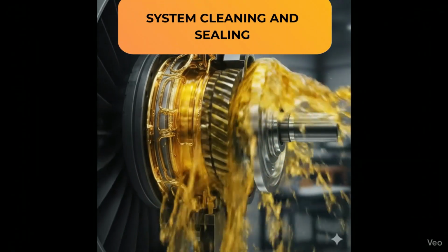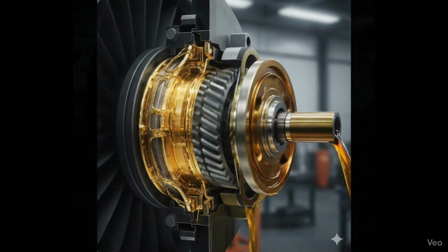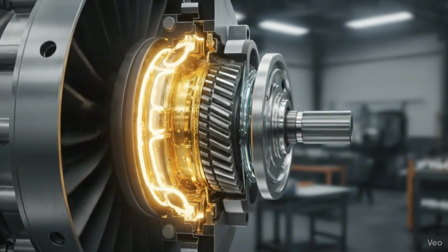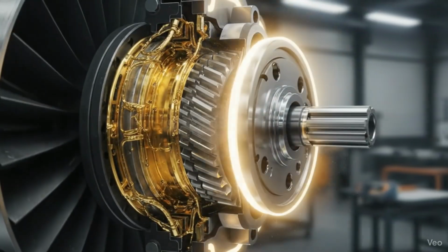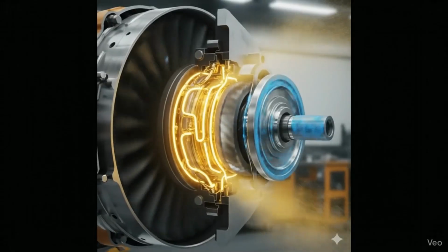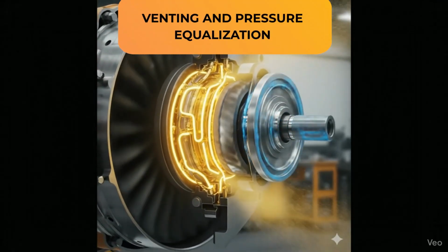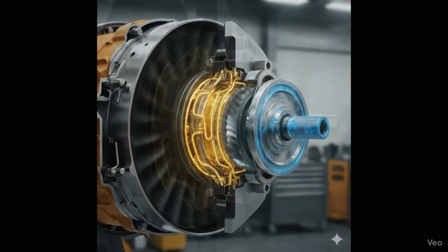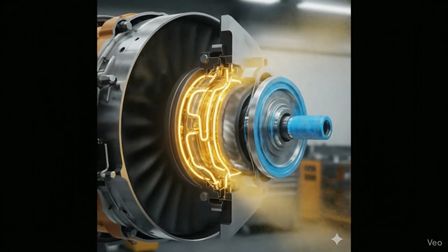System cleanliness and sealing. The oil flushes microscopic metallic wear particles away from the rotating components. Furthermore, it provides sealing in specific areas to prevent the ingestion of external dust or foreign particles. Venting and pressure equalization. Lubrication systems also incorporate vent lines to balance internal pressures. This prevents the buildup of excessive pressure within the bearing chambers.